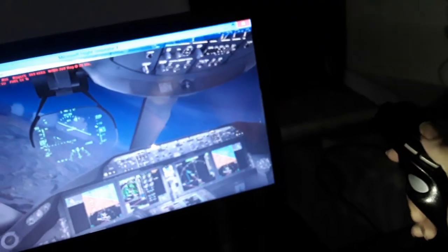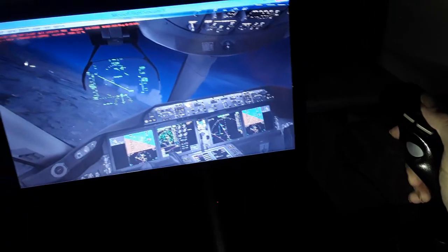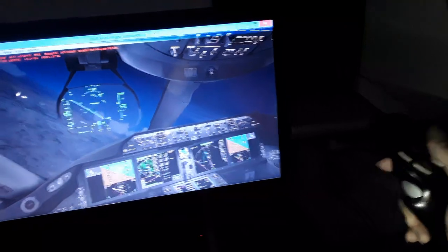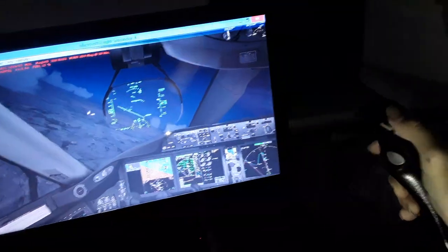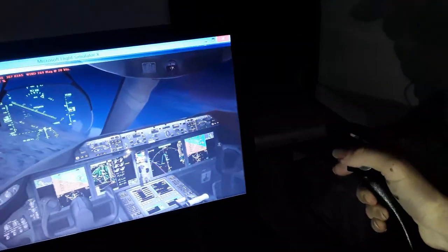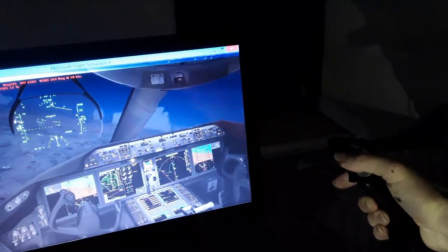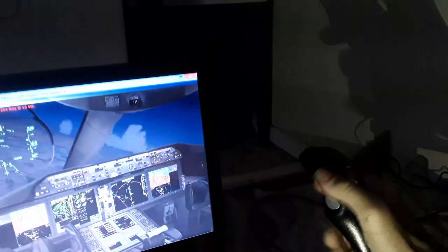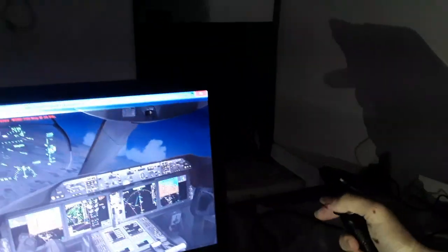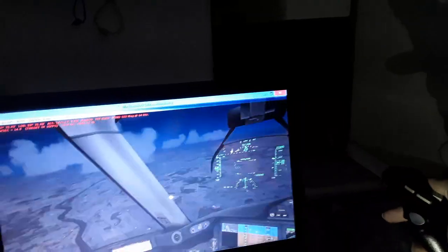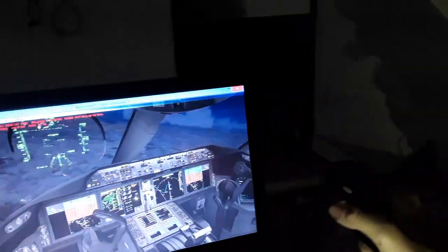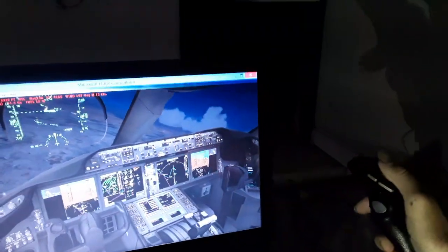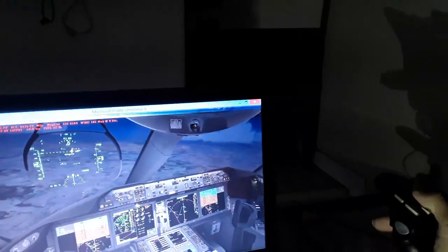We need to align over here with the runway setting. Also use landing gear down now as we are approaching. And more idle thrust. Decrease a little bit the rate of descent. A few more flaps over here. Flaps and slats. Some speed brakes.